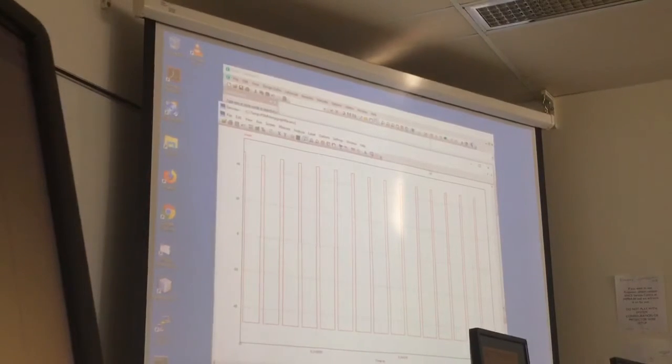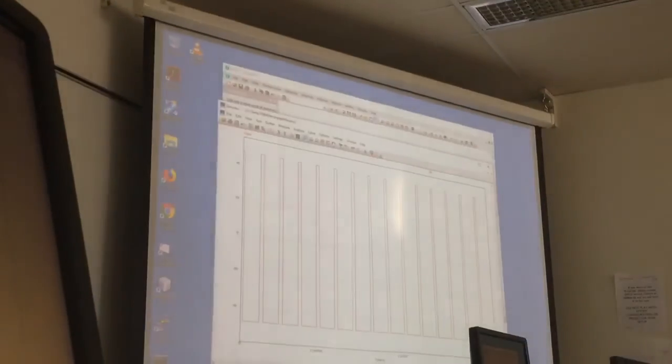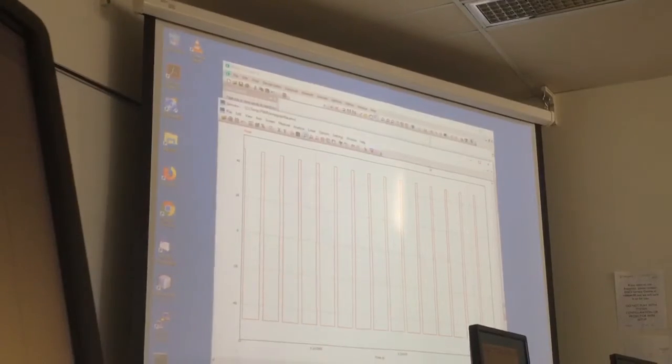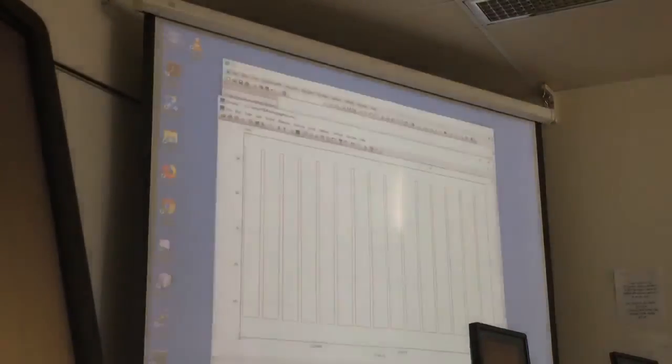Maybe it's about your time step. See, if you have more points, you're going to have more detail, but it seems you don't have a lot of points. So it's just going there and coming back. You need to have more points to increase the definition here. I hope this is the problem.